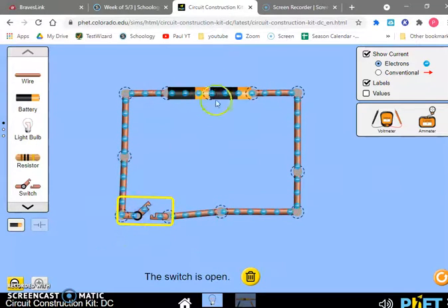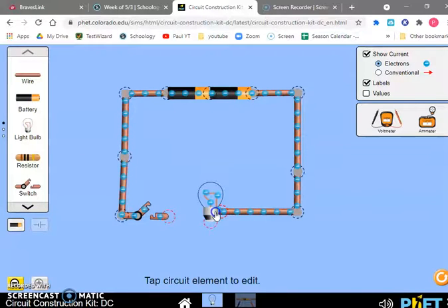A little bit extreme here, but the point is we have what is called a short circuit. In other words, the battery is not only our input, but it's also our output. The energy is being delivered here in the form of thermal energy, so the wires will get really warm, and in a 120 volt source in your home, that will cause a fire. So you always have to have a load where the energy is deposited. And we're going to learn it doesn't have to be just one load, you can have multiple loads, but we're going to start with the simplest possible case.